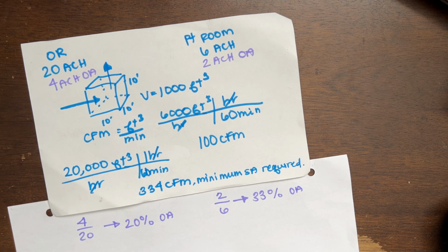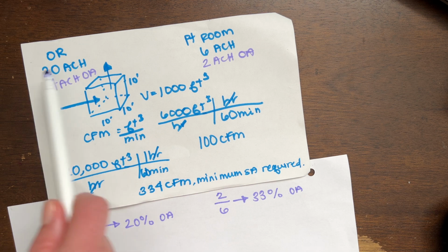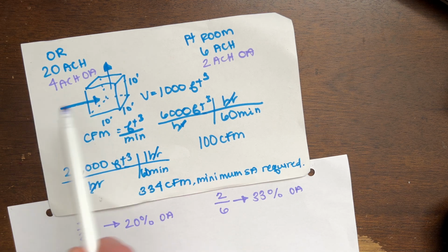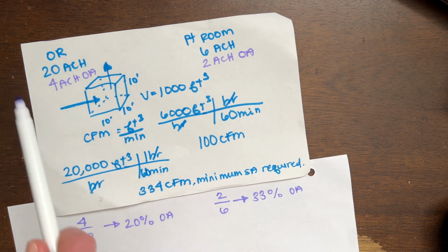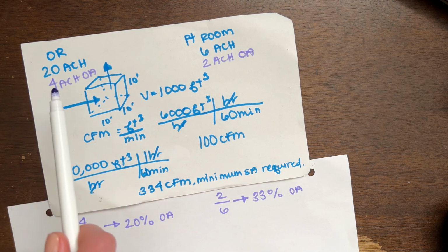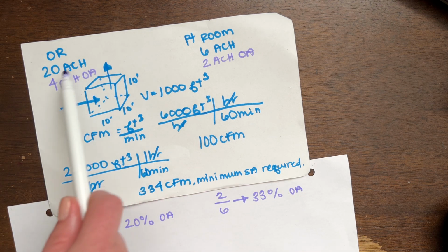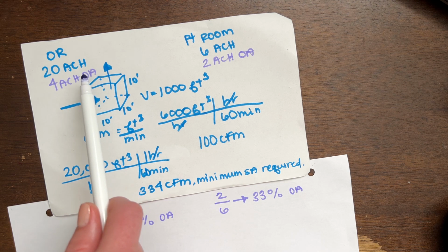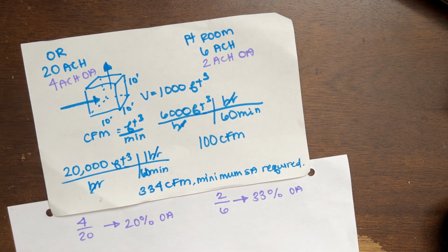There are other code requirements where your operating room has to have a certain filtration, HEPA filtration, and when it's moving all this air 20 times, it would rather maintain the clean air that's going through filtration going back to the space, as opposed to introducing more ventilation air. Ventilation air is derived from understanding the amount of people in a space that need fresh air.